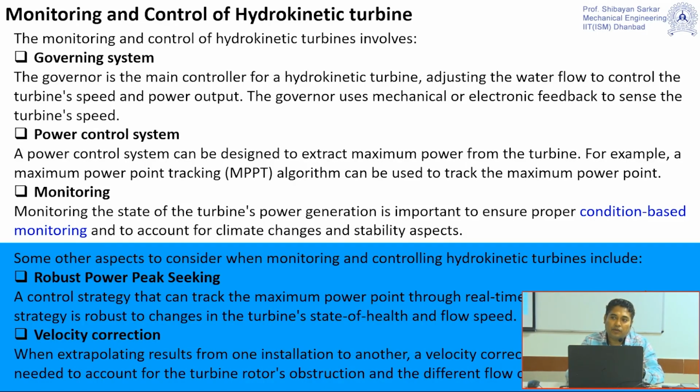Adjustable blades are not generally observed in water turbines, because there are other issues. If you put a controlling part in to adjust the pitch angle of the blade, it may happen that the water is directly carrying some impurities, or maybe some broken tree parts, so it may clog those particular systems. So generally people try to keep it fixed, but you can still control the governing mechanism, that means the entrance of the fluid inside the cavity.